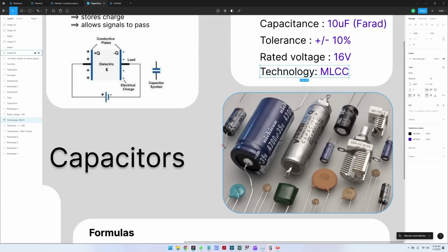If by any chance they are placed on the other side, it would cause this capacitor to explode. Also here you can see, so these are with terminals on opposite ends. With the terminals on the same end, which are more common, you can see here this is a 35 volt 4.7 microfarads capacitor.